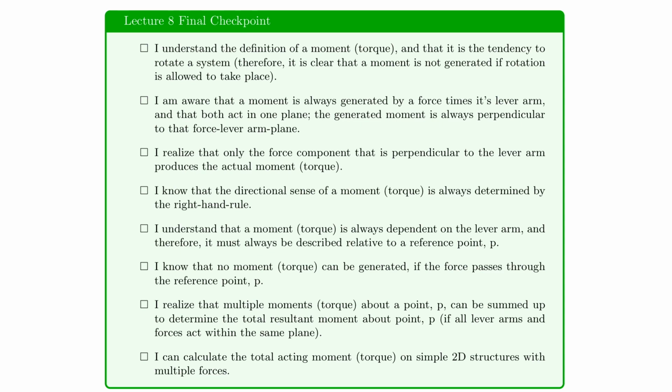First of all, we definitely understand the definition of a moment and that is the tendency to rotate. And the key word here is tendency, because if rotation is allowed, then it would create no moment. So we can check that off. We definitely understand that. We are also aware that moments are always generated by a force times its lever arm, and that both of these, the force and the lever arm, have to act in the same plane to generate a moment that is perpendicular to that force lever arm plane.